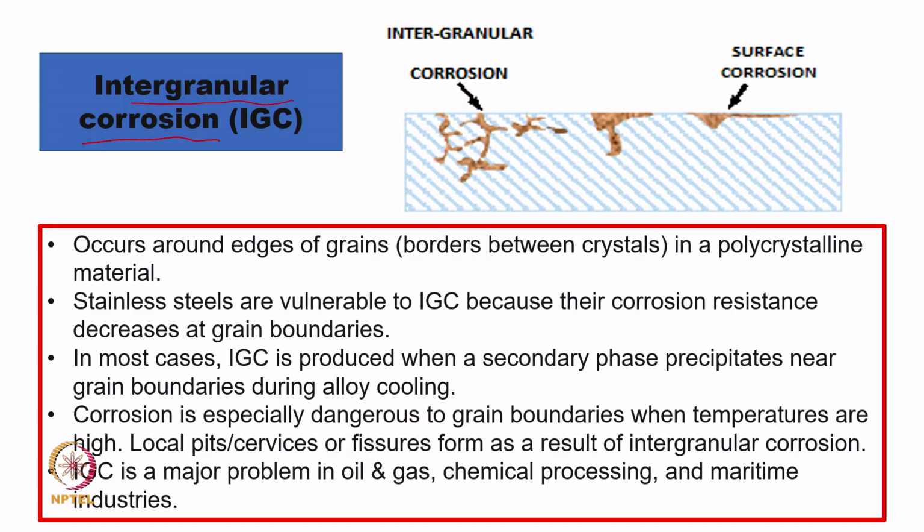Just to differentiate, I am showing here a surface corrosion, and you can see this corrosion is going deeper and deeper into the surface. This is intergranular corrosion, because corrosion requires some sort of route to pass, and the weak grain boundaries provide a good path for it. Quite possibly a whole chunk will come out and make a pit, which will be called pitting corrosion.